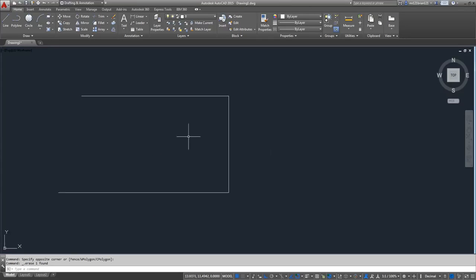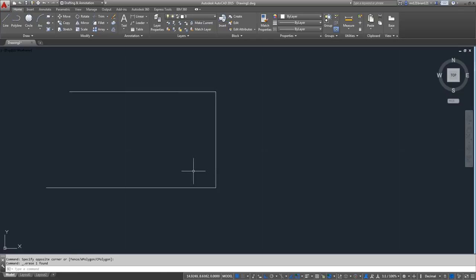Something that you should know when using AutoCAD, you have to activate the OSNAPs. OSNAP is the abbreviation of Object Snap. What is that for? Well, you can see if I'm making a line, or just when I was using a circle, my cursor is displaying a green button, and here another green, and here another green button. Those are references that we are going to use in AutoCAD, and they are very, very, very useful.